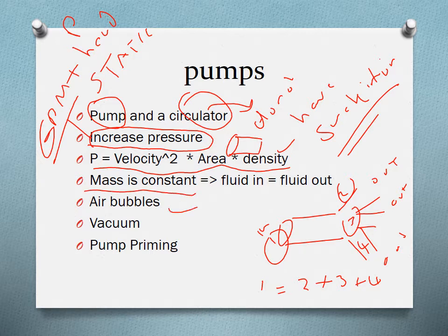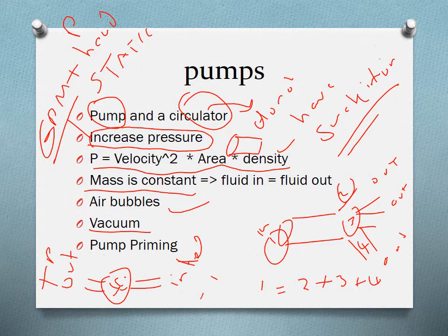Air bubbles are problematic for pumps. Pumps are designed to pump liquid, not air. If there's air, the pump might not work properly. Some pumps do not work in vacuum, meaning that they will not suck liquid if there are bubbles in there. And also, if we look at a pump, let's call this a pump here. There's an inlet and an outlet. So here we'll have positive pressure, and here we have negative pressure, and negative pressure is always called a vacuum.